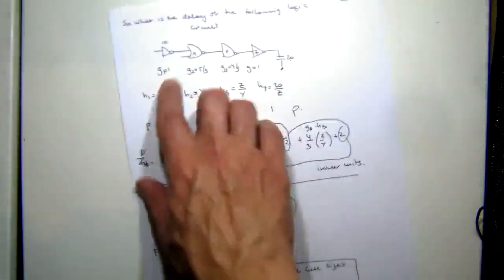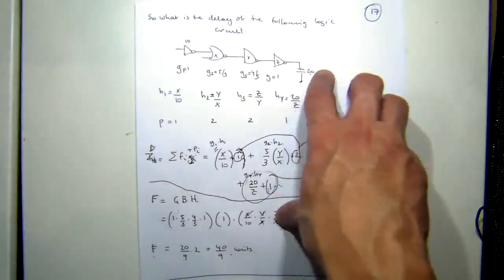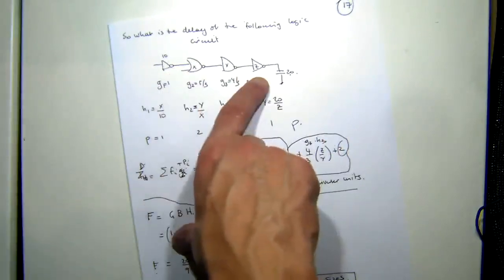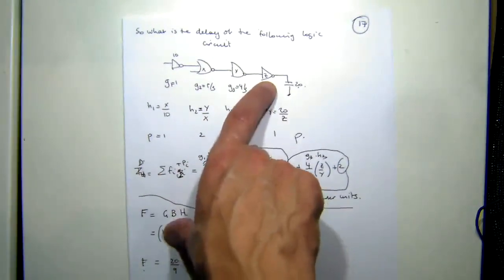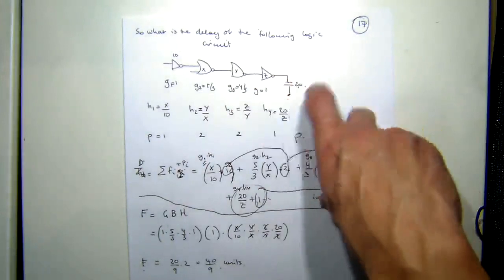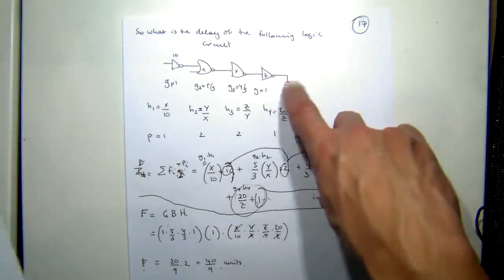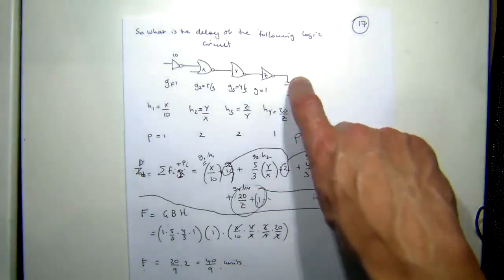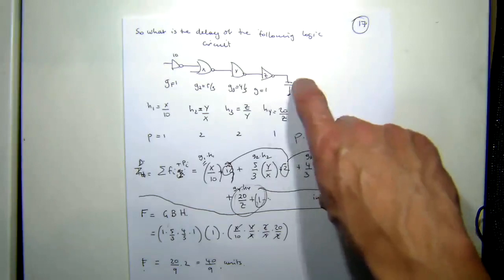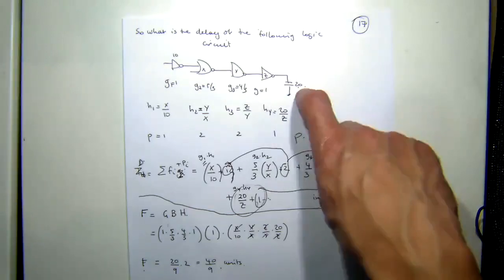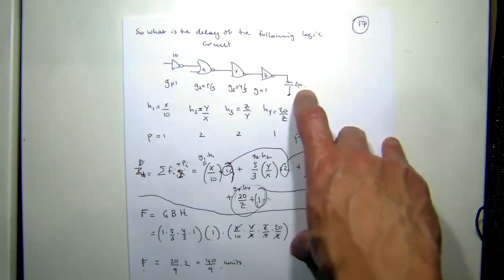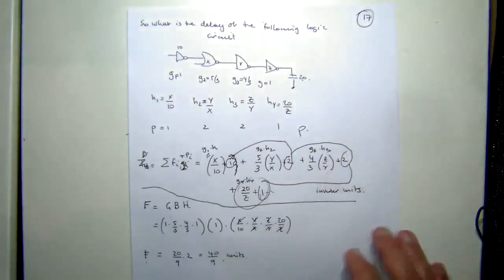And we did an example of how to actually work out what delay we would expect through this relatively simple logic circuit, including something that we've mimicked as the load, where we're approximating it as a capacitor of 20 units. And again, I re-emphasize, 20 units is equivalent capacitance to an inverter in the minimum process.